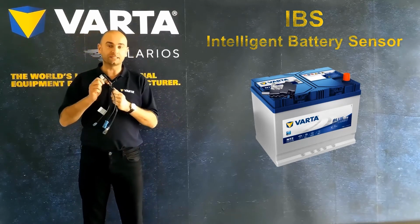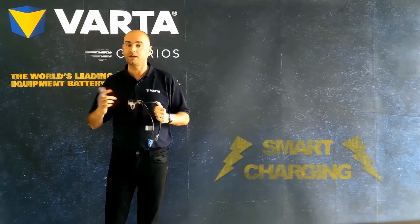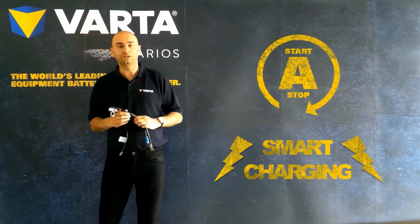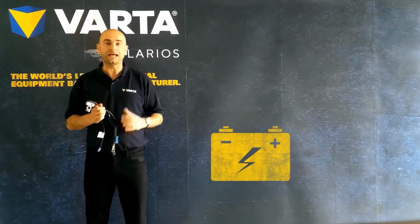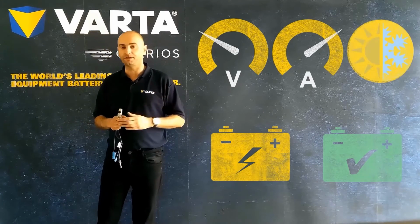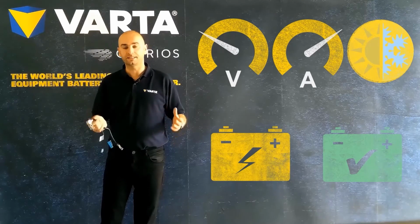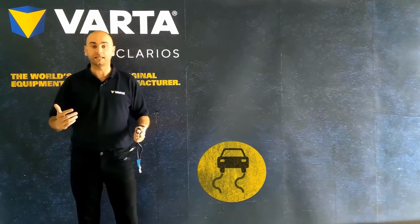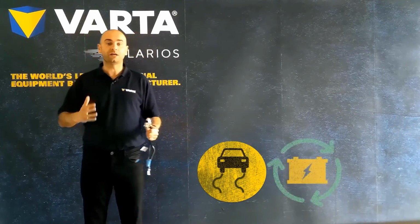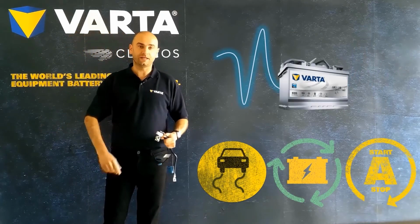By identifying this sensor correctly connected to the battery, it is an indication that the vehicle has either smart charging or start-stop capabilities. The IBS is used to determine the battery's state of charge and state of health by measuring the battery's voltage, current and temperature. The energy demand on the battery depends on the equipment level fitted on today's cars. Systems such as ADAS, braking and fuel-saving functions such as coasting, plus energy recovery and start-stop. After all, the battery is the heart of the vehicle.